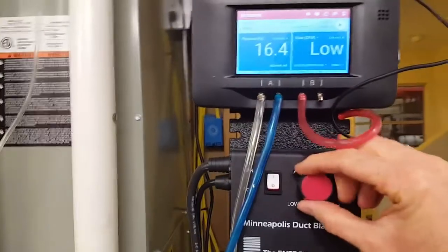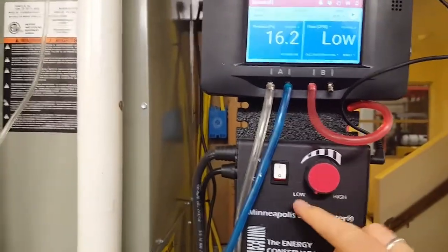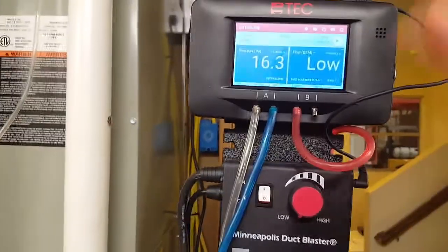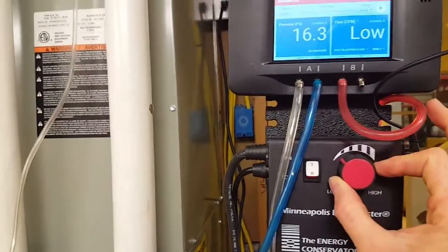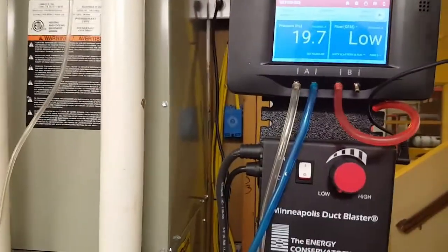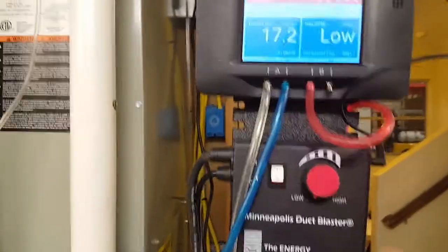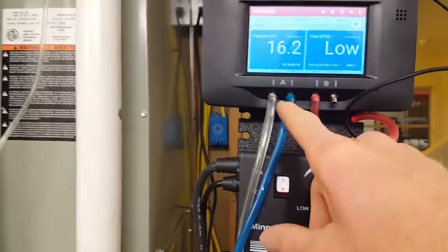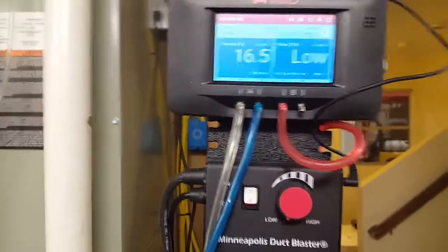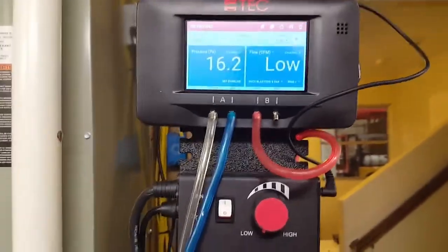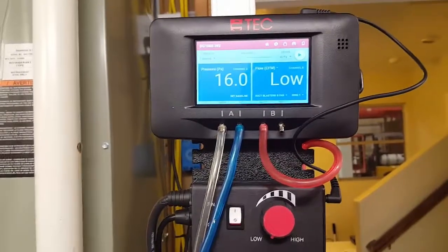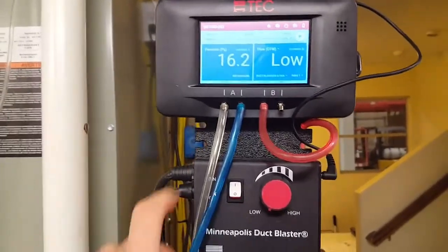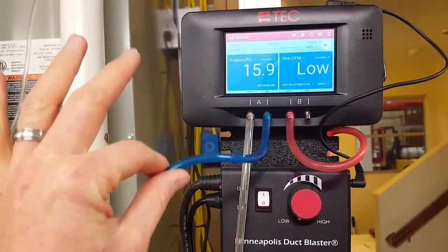So the duct blaster set, you put the dial just down here so it's just barely on, and that way we can run it remotely. If you turn it up at all, it'll run the fan speed, but it won't do the cruise control. So you gotta leave that there. And then as soon as we connect, we'll run all this remotely. But one of the things you've got to do, if you're going to use the software to run your duct leakage to the outside test, you have to reference the outside.